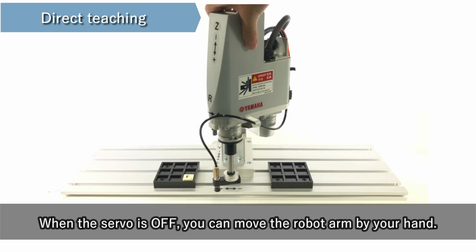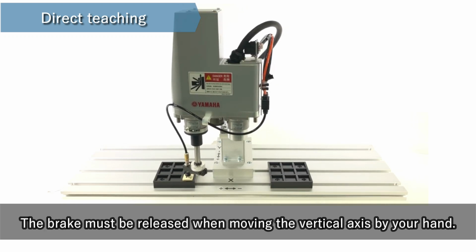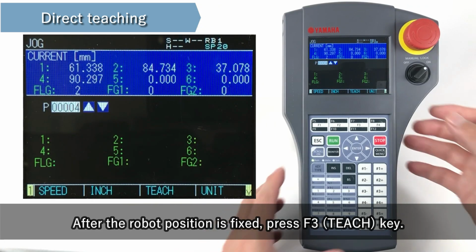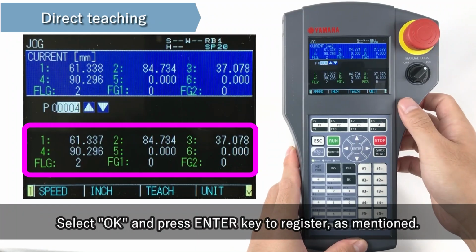When the servo is off, you can move the robot arm by your hand. The brake must be released when moving the vertical axis by your hand. Please see the movie servo operation for how to release brake. When releasing the brake, be careful not to pinch your hands or body as it may fall due to gravity. After the robot position is fixed, press F3 key. Select OK and press Enter key to register, as mentioned.